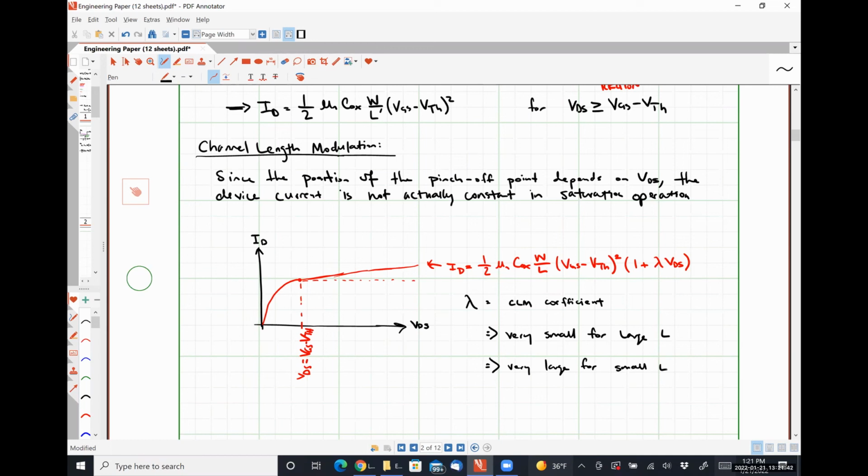All right, I think that's all I'm going to talk about today. I have a page and a half of notes on sub-threshold current operation, but I've never actually seen that used in a single problem in any textbook or anything like that. So it's more of a general information. And effectively, all sub-threshold current means is that even if you don't have strong inversion yet, there's still some charge carriers in the channel. So if you applied a potential difference between the drain and the source, a very small amount of current will flow. We could beat it to death with math if we wanted to, but there doesn't seem to be any point because there's never anything beyond that.